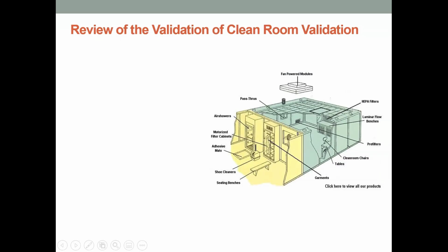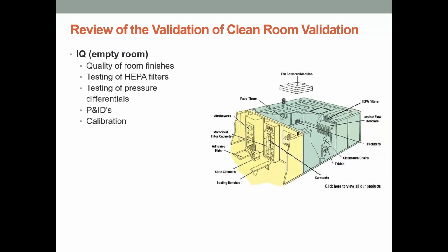So just to have a little review of what we have looked at for our clean room validation through the last few lessons. We talked during the IQ phase of what we would do in the empty room. We looked at the quality of the room finishes. We looked at the testing of the HEPA filters. We looked at the testing of the pressure differentials between the room and the rooms beside it. We looked at the P&ID drawings, and we looked at the calibration as well.